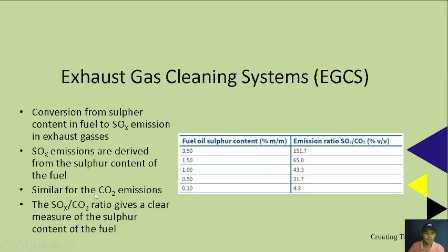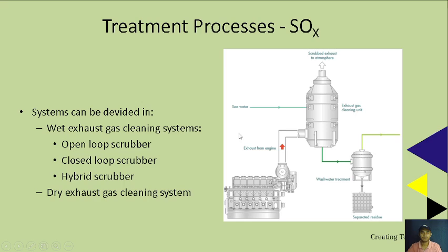So similar for the CO2 emissions. So the SOx to CO2 ratio gives a clear measure of the sulfur content of the fuel. So fuel oil sulfur content, percent mass per mass, and emission rate, sulfur dioxide and carbon dioxide, percent of volume per volume.